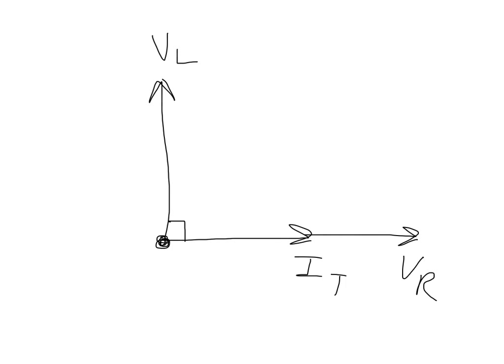What does change is the source voltage phasor. And what causes this change is the inductor. The source voltage phasor is actually going to phase shift in front of the total current by a certain amount, which is phase angle theta. The inductor is what causes this phase shift.